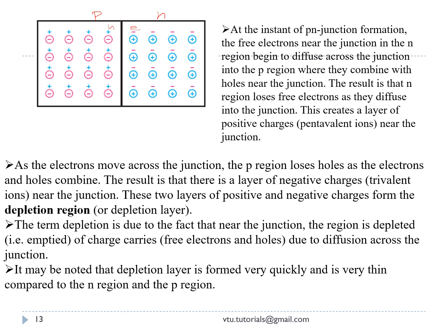When these two semiconductors are joined together, these free electrons will diffuse and recombine with the holes. All the electrons near the junction jump into the holes and form bonds there. This atom will be depleted of an electron and it will become positively charged. So the atoms here will become positively charged.